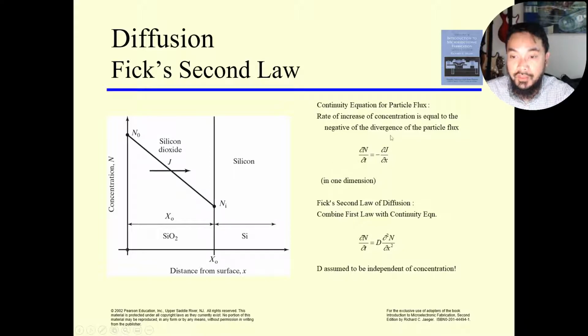With this, you can get what we call Fick's second law of diffusion, whereby you combine the first law and the continuity equation. Diffusion follows Fick's second law rather than the first one. One thing to take note of is that D, the diffusion coefficient, is assumed to be independent of concentration.